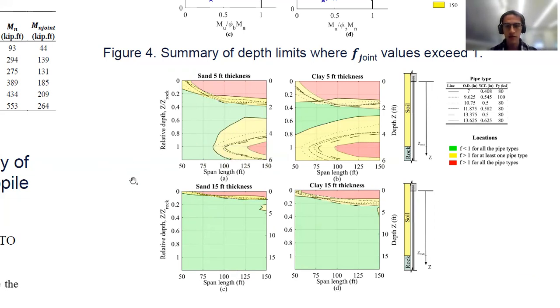Again, we know in this case, increasing bedrock depths now provide a more detrimental scenario. That's because we are allowing loads to dissipate all through the depth, so that increases the loads at deeper locations, while stiffer soils are more convenient because those dissipate loads more easily.